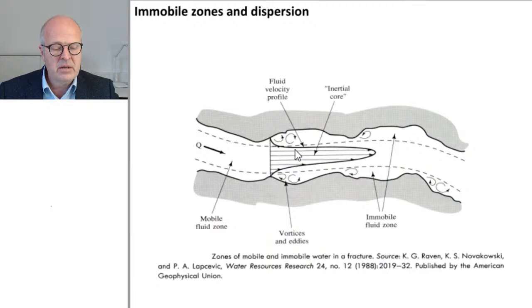What caused the irregular shape on the right hand side? Yes, simply imagine an aquifer, a normal aquifer. You have sand and gravel and maybe a clay lens. When water flows through this sediment, it will also be dispersed in a different manner in gravel, in sand, and in clay. And because the aquifer is not homogeneous, you actually get additional dispersion, irregular dispersion, as evidenced by this graph on the right hand side.